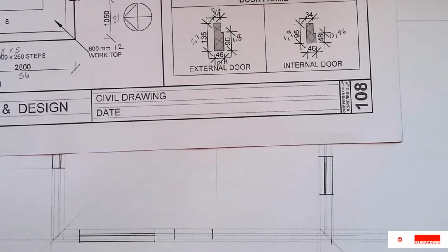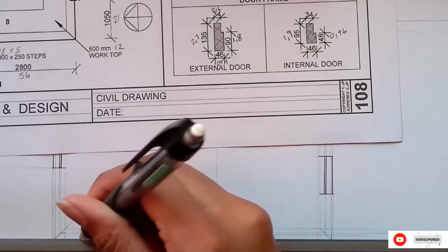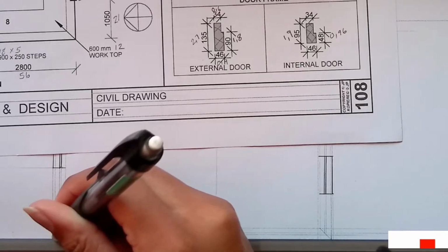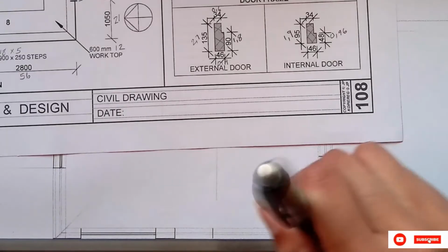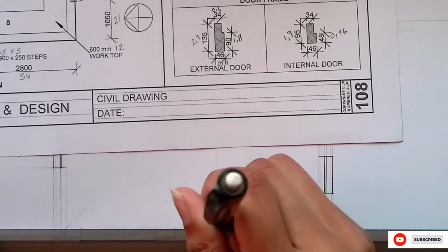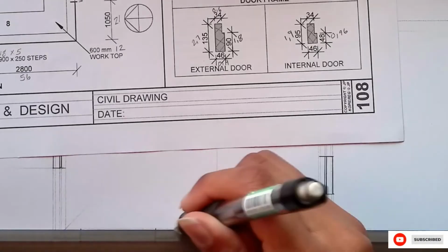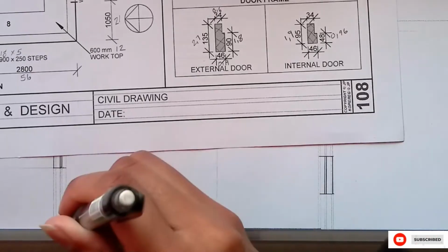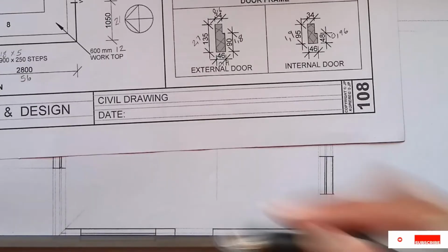So with now me knowing the space for my door, let me just extend this wall. Then also extend it to the side. So at least I know that my wall is here. My wall is here and my door is in this space that I now need to use to draw the frame. So with the frame, we use the center of the wall.